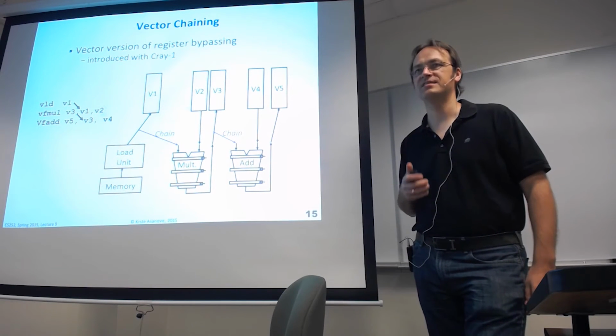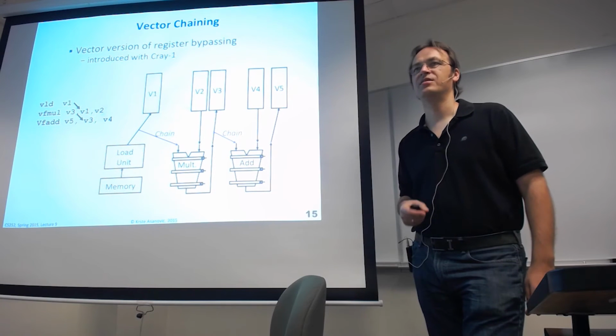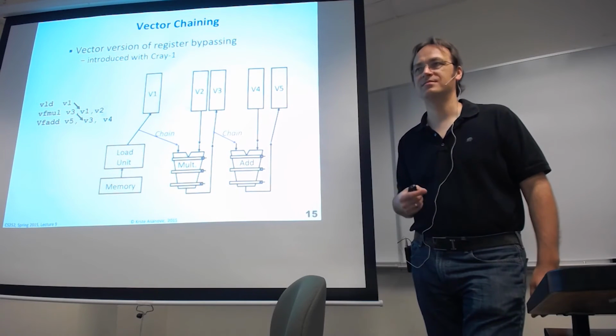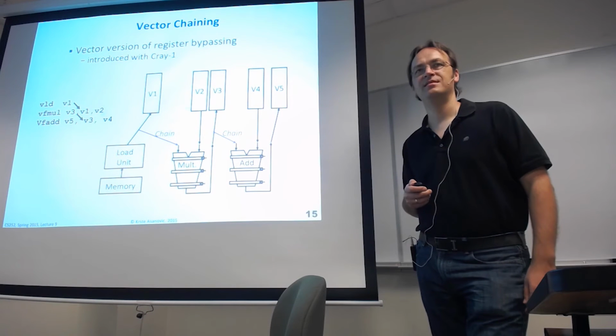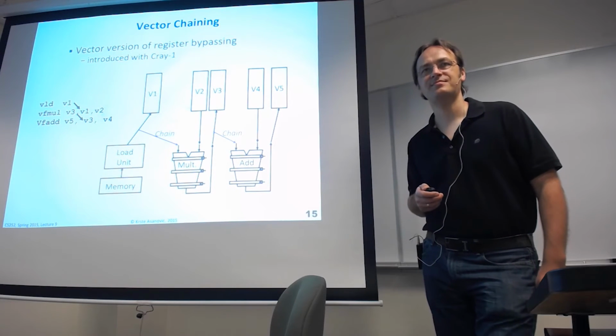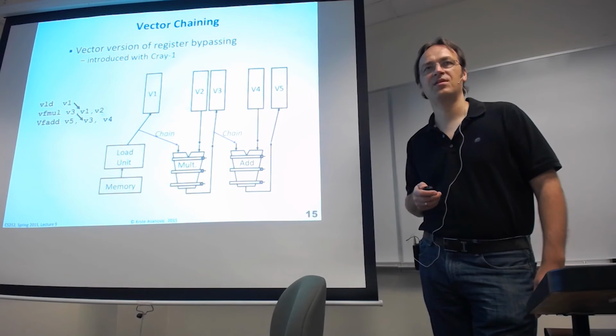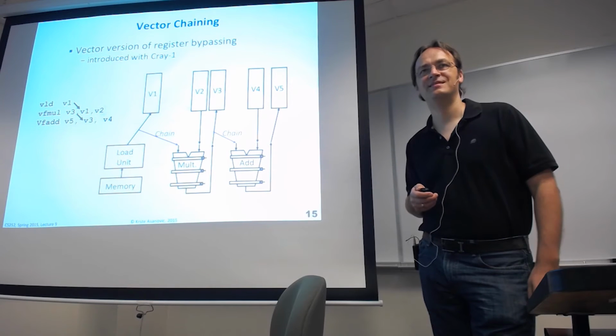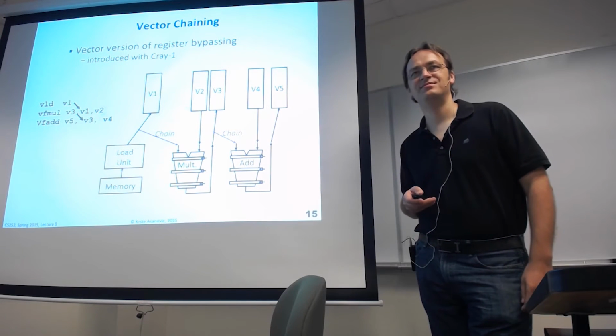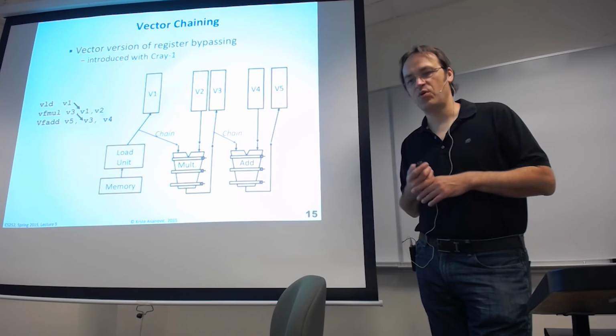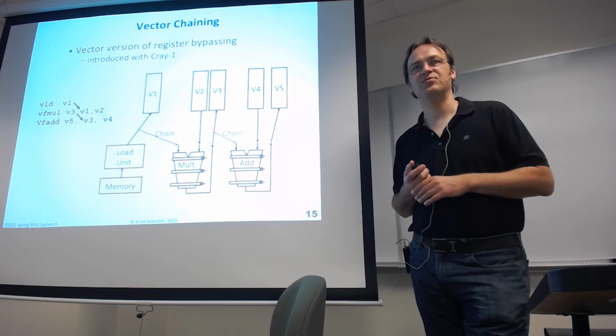So I want to read and write the same vector register in the same instruction, but I only have one read or write port on the vector register. Some temporary storage to buffer the result, yeah, you need somewhere else to temporarily stash the result until you write back in the same register. Right? So one possibility is you have some extra storage to hold the result.